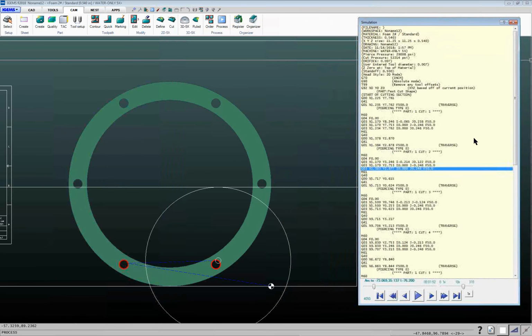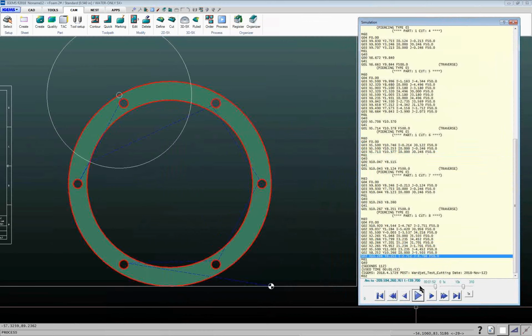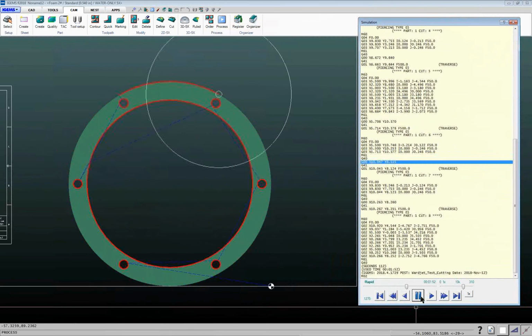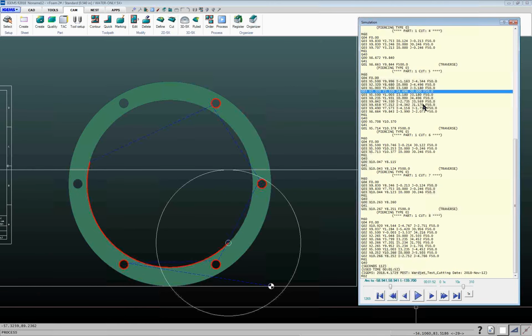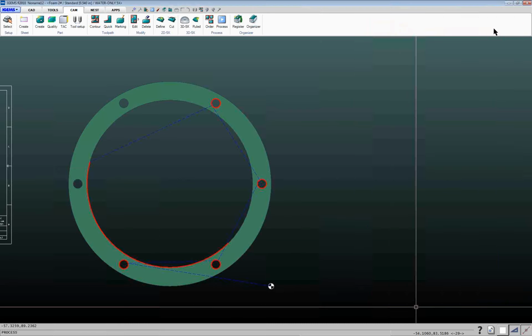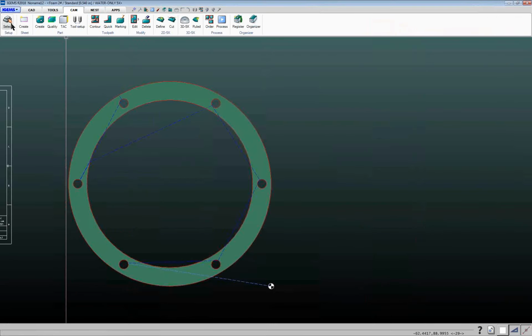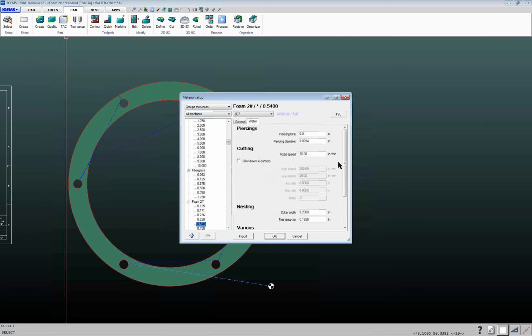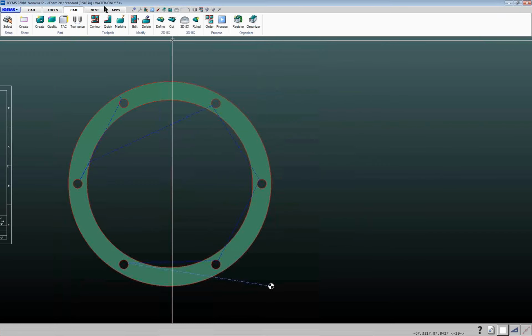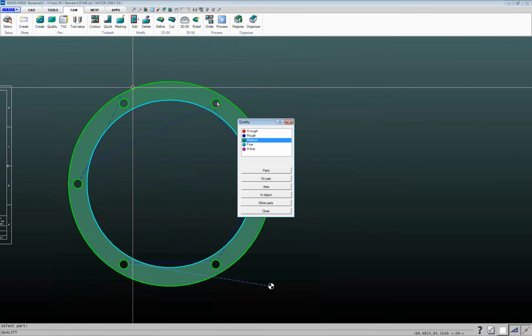So let's see, get around to that cut here. So that was pretty fast. Try that again. Was it this cut here? So even though I told it a different quality, it's still at 50 inches a minute. But what I did for another customer who was water only was basically adjusted the post and said, all right, if you flag it as being a different quality, then it can use either this high speed or this low speed. And I don't know if this post that I have right now will allow me to do that. Let me see, I think it might.